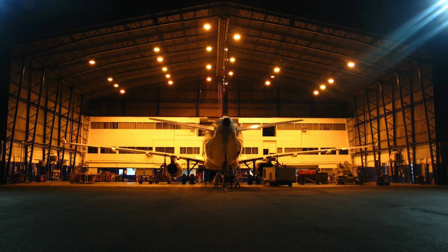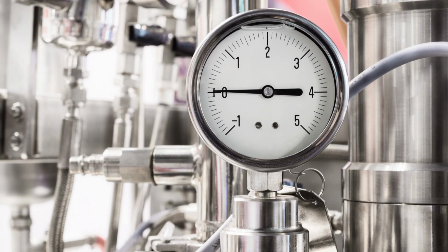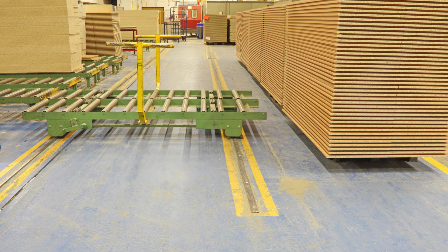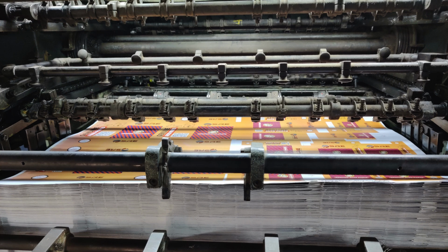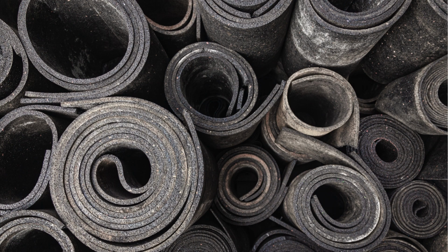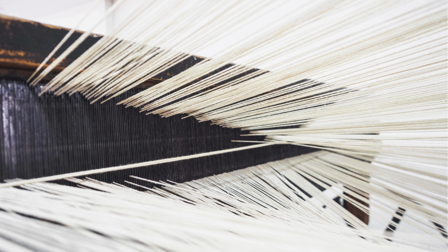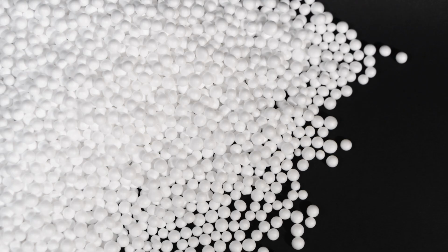Group 1: aircraft hangars, except as governed by NFPA 409. Combustible hydraulic fluid use areas. Die casting, metal extruding, plywood and particle board manufacturing. Printing, using inks having flash points below 100 degrees Fahrenheit. Rubber reclaiming, compounding, drying, milling, vulcanizing. Sawmills, textile picking, opening, blending, garnetting, or carding, combining of cotton, synthetics, wool shoddy, or burlap. Upholstering with plastic foams.